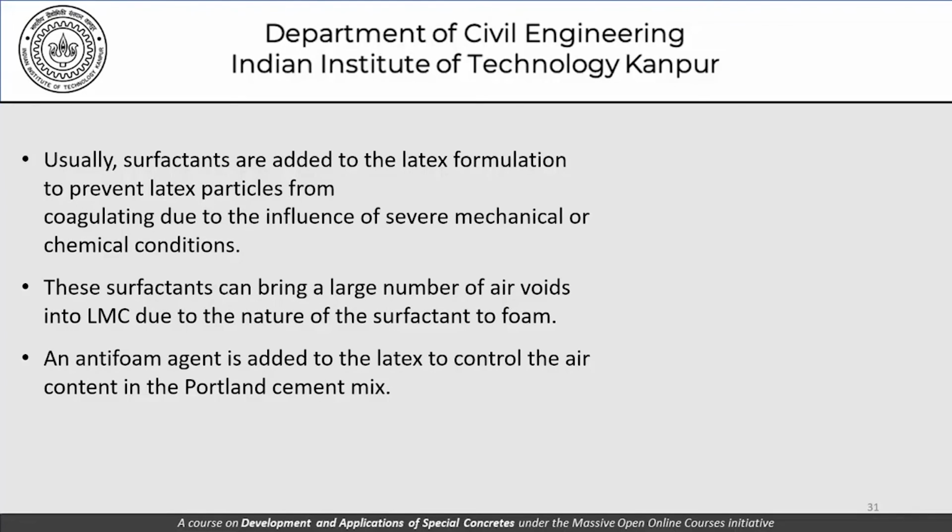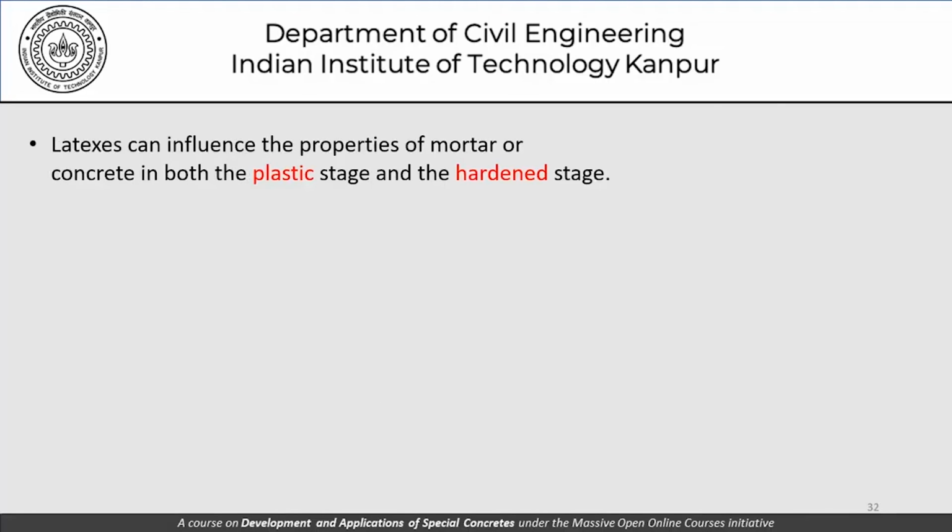So if we are using latex particles and we use surfactants to prevent the latex particles from coagulating, those surfactants will have the side effect of creating a lot of air voids, and therefore we need to use anti-foaming agents. That's what's listed here.